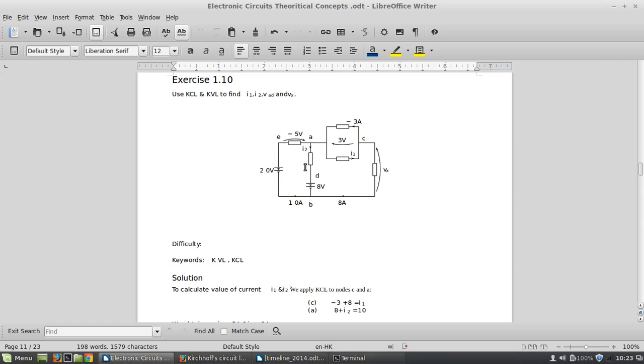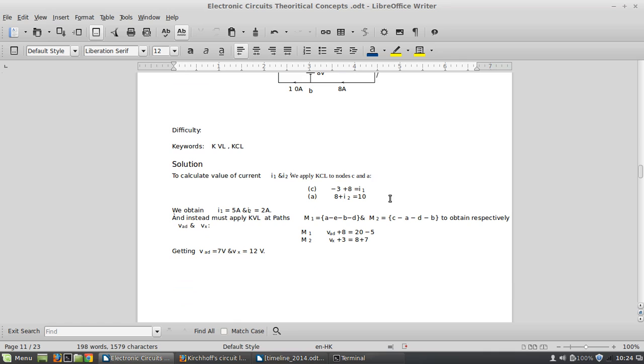Okay, I got the technique. The technique is this node or junction can be used because there is this current I1, which is the only unknown here, and there are two knowns. There are 3 ampere, and the current from here, that is I8, is here. Alright, so here it is done. By solving this junction we find I1.